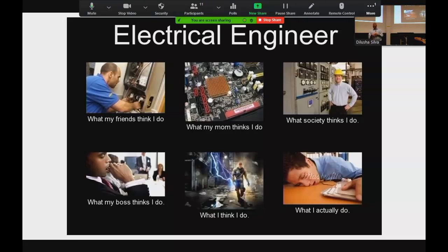But they're not, again, I have to use the word sloppy in terms of their use. I wouldn't overly rely on them. They're great for short circuit protection, but if the thing's sitting on a partial fault, it will just sit there all day long, smouldering. All right? Anything else?